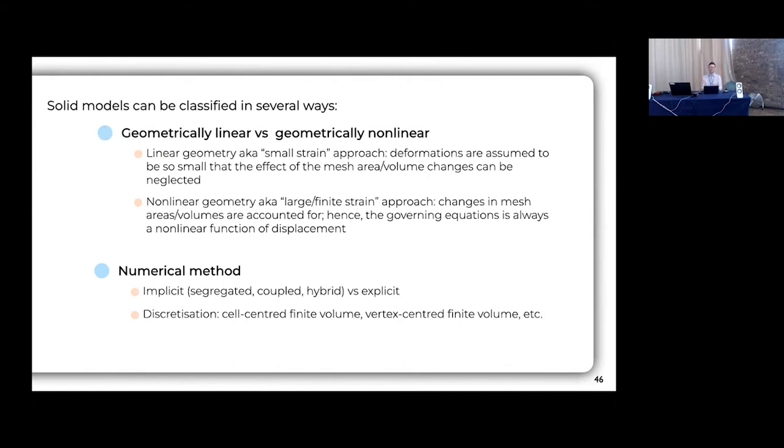And what does that mean? It means our equation, we're integrating over a volume. When I apply force, it moves a little bit. And the area of that infinitesimal piece of surface will change. So that means if we're integrating over that surface, it's unknown. So we're integrating over a mesh that we don't know yet. That means solids are always inherently nonlinear, because that's a function of displacement, and your stress is a function of displacement. You multiply them together.